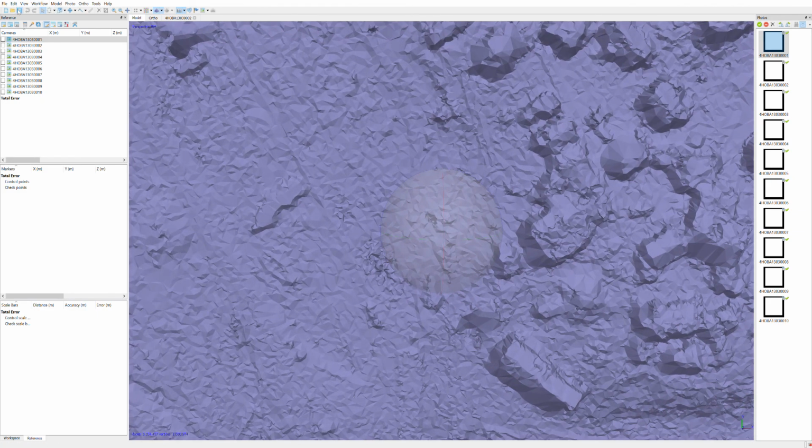So we will save and now build our ortho, and the projection will be top XY, planar. You should be able to leave everything alone. The surface is mesh and will blend with the mosaic. Definitely enable hole filling, and you could refine seam lines. I'm not going to, it just takes more time. Notice that the pixel size is ridiculously small, again because it's not projected. It doesn't know how big this image actually is. So just leave everything as default and press OK.